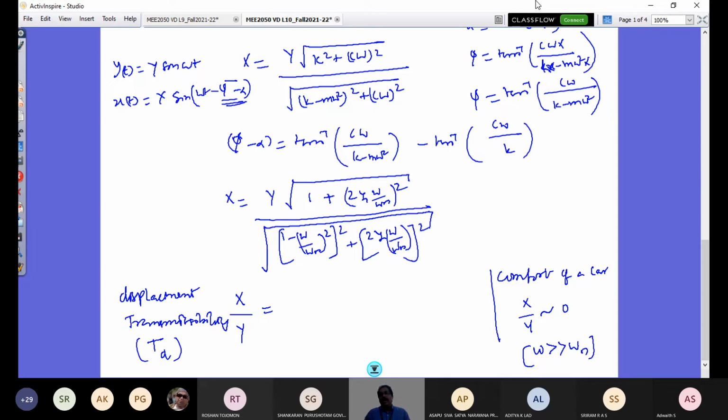But the endurance test, durability test of your vehicle is tested that you have to go over a bump, correct? A speed breaker. So that speed breaker, when you go over, that's kind of a large cleat and it would excite a strong impulse. But if that is continuously made on a road, you see your vehicle would always have excitation in a sinusoidal wave, and such kind of test tracks, patches are there.